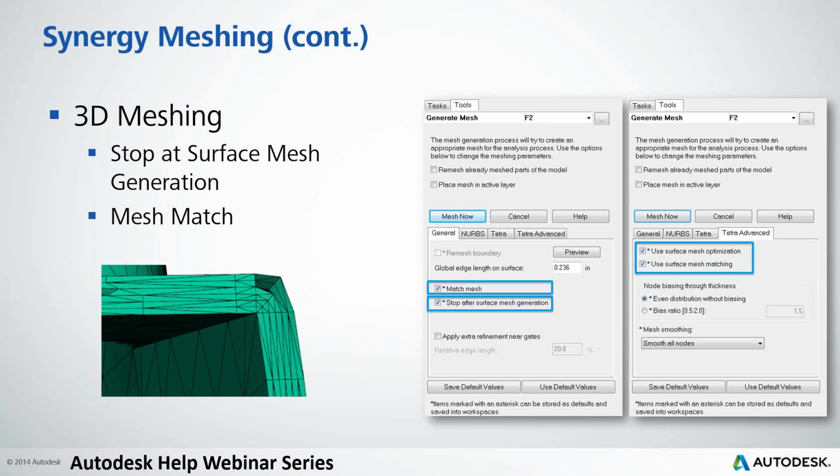And the only reason we suggest that sometimes, or most of the time, is to, again, catch those issues before you mesh it to 3D, because 3D mesh can be a little tricky to work with sometimes. Say you're merging nodes or elements together, and it might cause collapses in the internal mesh or something. So again, doing that gives you a checkpoint before being able to move forward.